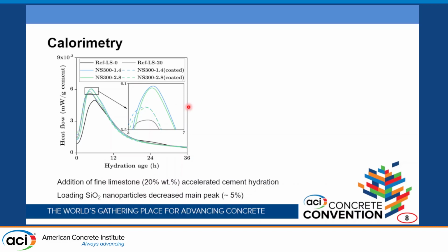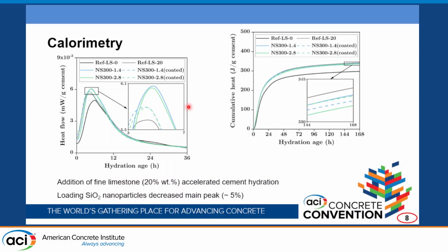But the important thing is that when we coat limestone with silica nanoparticles, we are removing the acceleration effect caused by using very fine limestone particles. That's why we got less effect from the nanoparticles in the coated state. You can also see an almost statistically insignificant increase in the cumulative heat, whether using nanoparticles in the coated state or separately during mixing. So there are no significant changes in the hydration kinetics of cement.